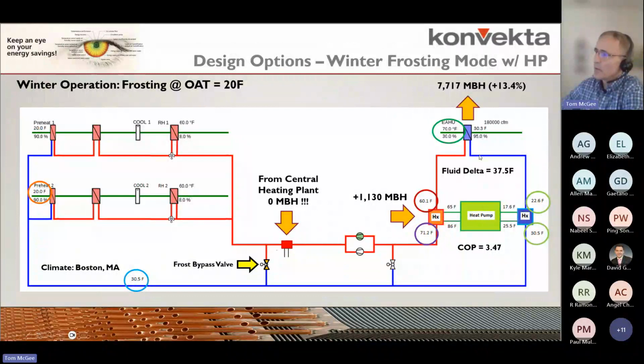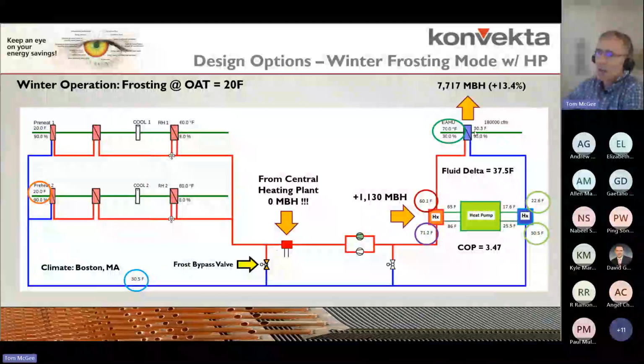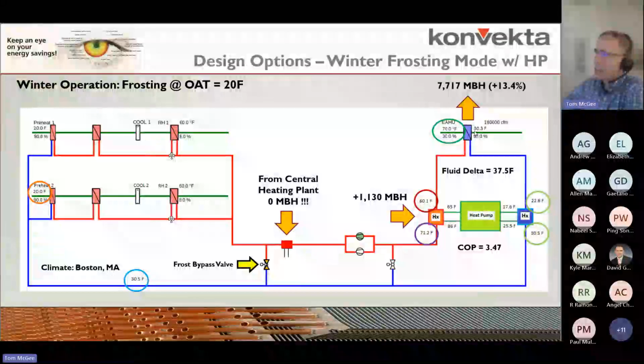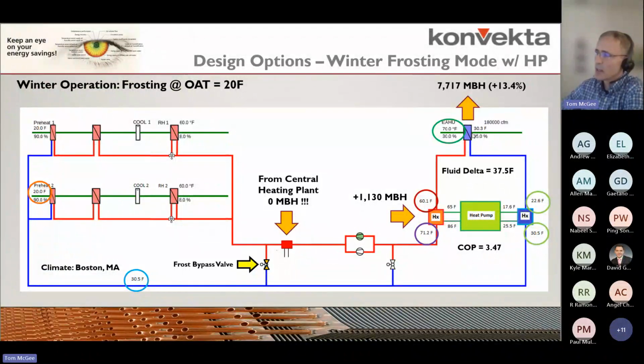And with frost defrost we were able to extract more, because we're going from an airstream, from gas to liquid to frost. So you're going through two phase transitions, and what that allows us to do is increase our net recovered energy.